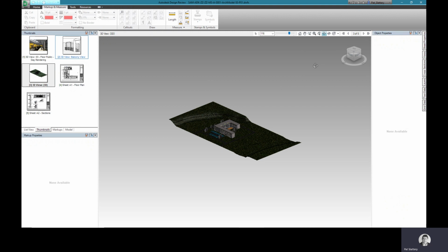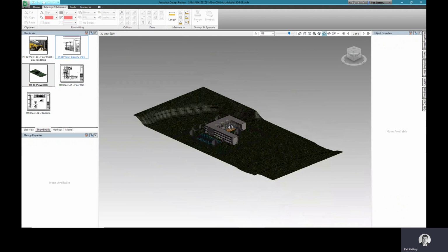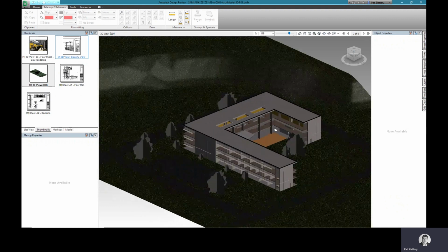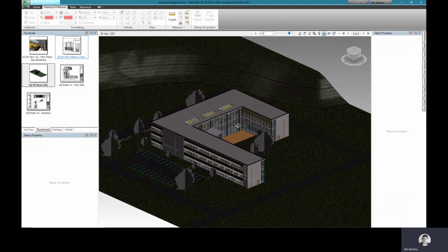In 3D views, you have a couple of extra navigation tools. You've got the orbit tool and the turntable tool. But most of the tools you need are available on the mouse. So we can zoom in and zoom out by just scrolling the wheel. We can pan from left to right by picking the wheel and moving the model from side to side. Okay. I'm just going to go back to the select button rather than any of the other navigation tool buttons.